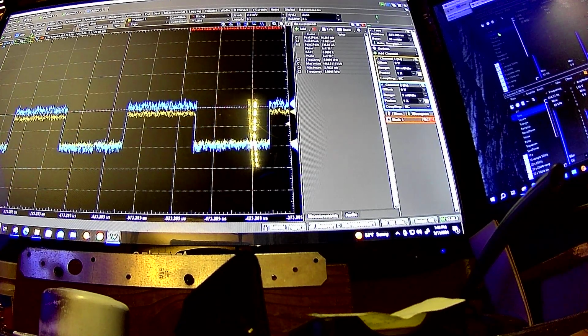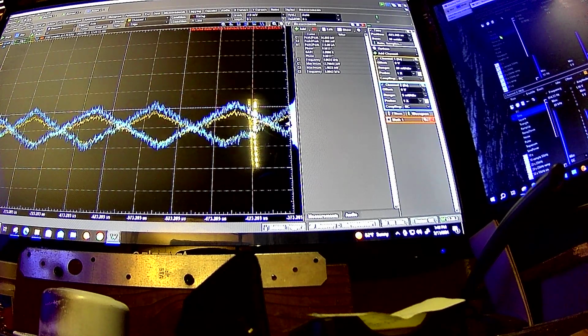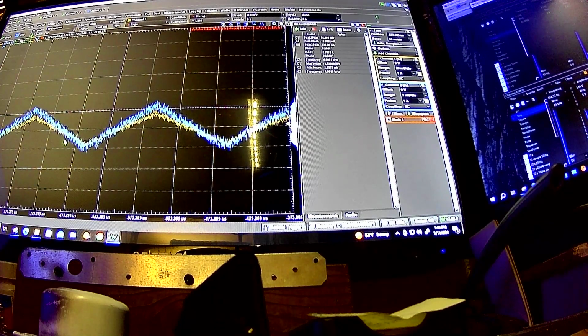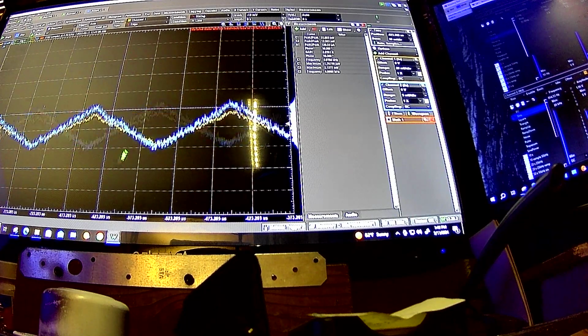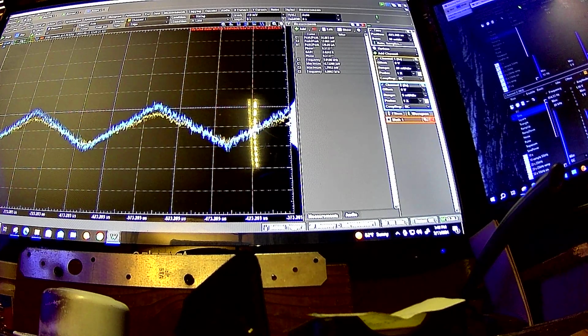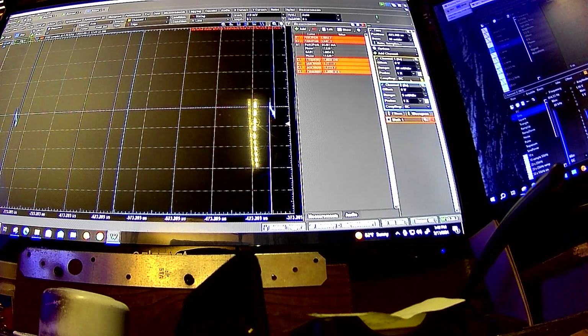So, like I said, they may be adjusting their analog reference to match their signal resolution so they don't lose as much vertical resolution. But normally, if you don't have complicated circuitry like that, a DAC will have resolution limits on what kind of how good your waveform looks, just due to vertical resolution problems, as well as frequency problems.